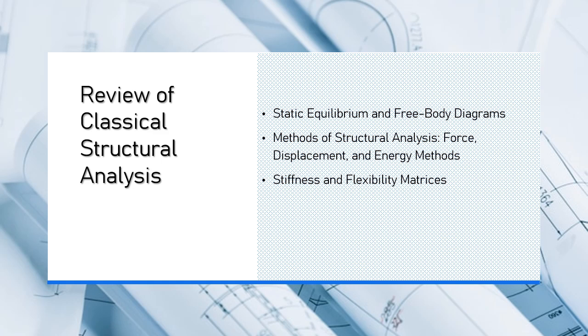2.5. Applications of the methods. Force methods are used when solving for internal forces is the primary goal, and when there are only a few redundants to deal with. They are often used for simpler structures like beams with multiple supports or simple frames where the complexity is not high.